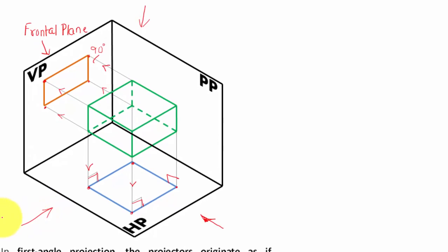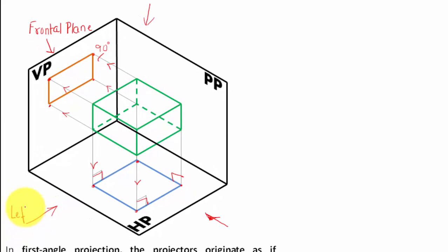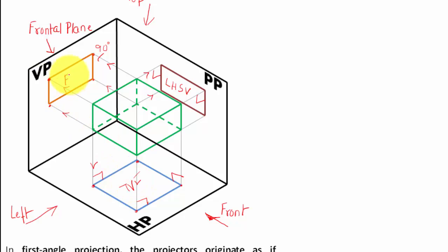object from here, from the left hand side. So this is left. Let me write this. This was about having the front view, so we had to look at this object from the front, and this was for top. Alright, now let's take a look at this object from the side this way, and hence we are having this. These are the projectors, parallel projectors, and this is the 90 degree angle. Alright, and we have a view, and in this case we are having a left hand side view. This over here represented top view, and this was all about front view.